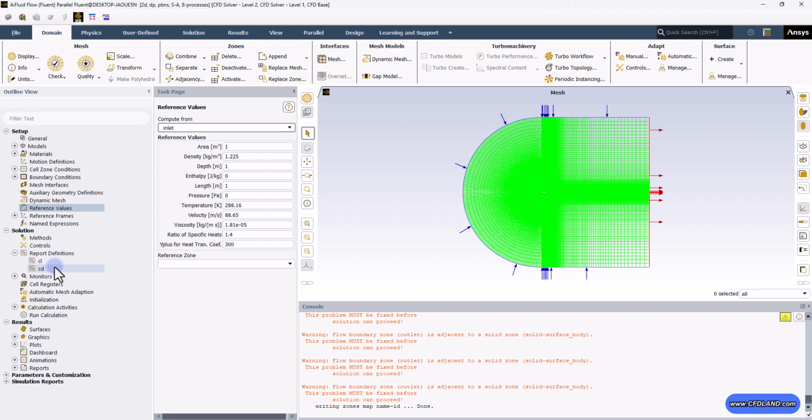There would be some constants that we need to set. And when it comes to airfoil simulations, this area does matter. This is exactly the characteristic length that we use and deploy in our formulation. And in most studies, we set the chord length as the projected area. So 1 is the correct value for our case, which has 1 meter chord.